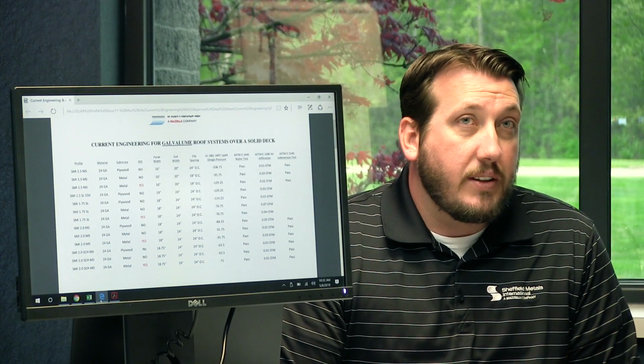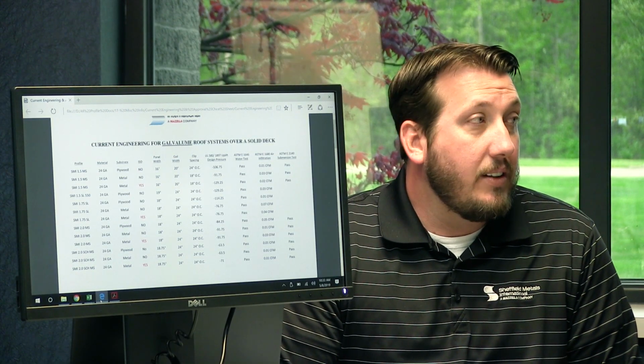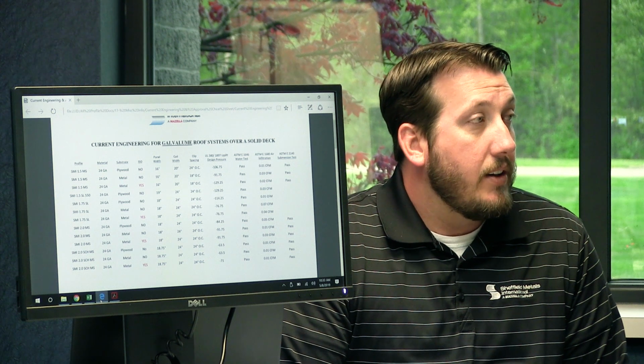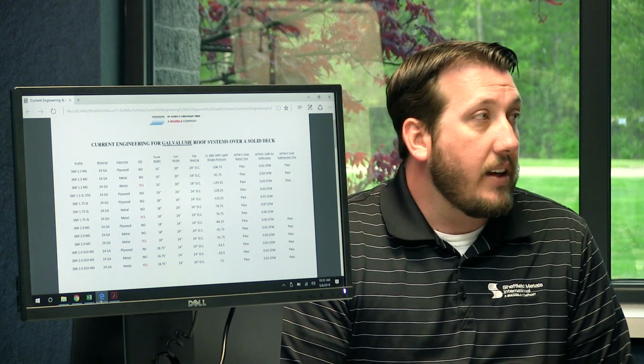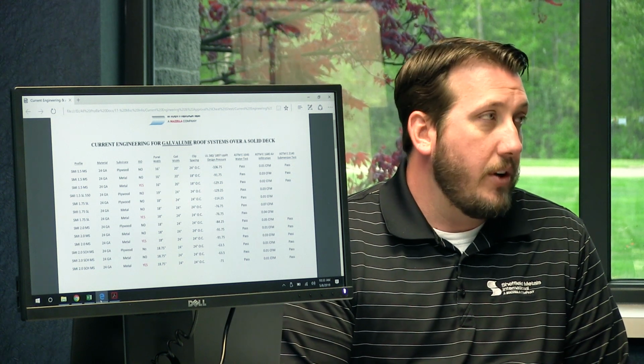To put things in perspective, a UL 90 rating needs at least a 52.5 design pressure in order to achieve UL 90. Okay. And these are all in negatives, so it's negative 200, negative 52.5. So what are exposure categories? Is that the next logical step here?